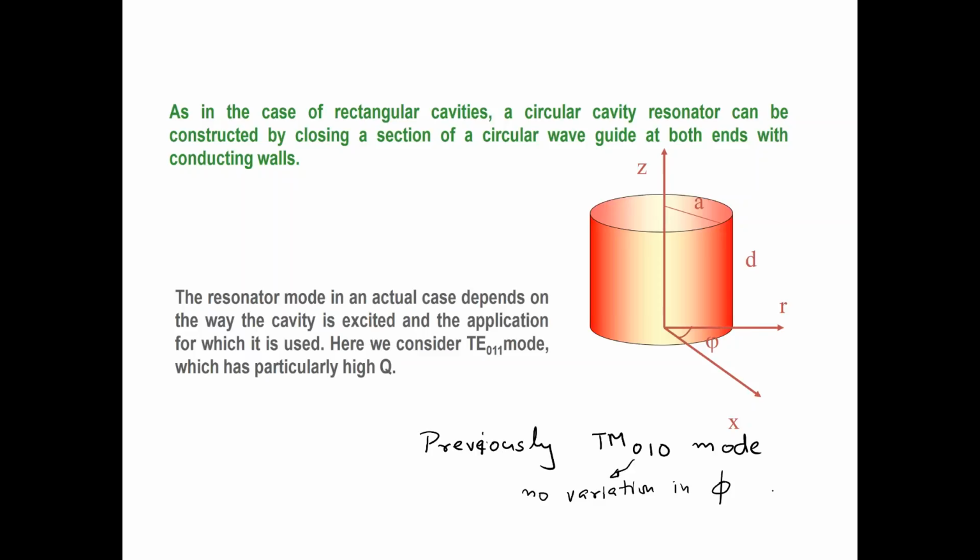and we're using the J0 term, the Bessel function of 0th order, and we are going to its first 0 point. So in the radial direction, the first 0 point has to be fixed there, and the last 0 means no variation in Z. So that's the mode we had looked at. It's the simplest mode to conceptually think about and mathematically solve for.